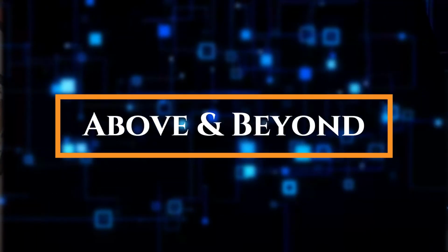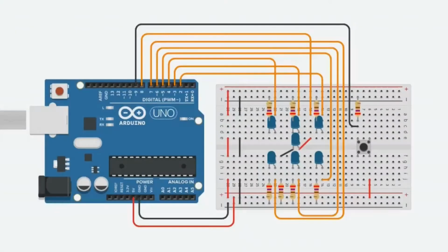Above and beyond. This circuit contains 7 LEDs, 8 270 ohm resistors, and a push button. This circuit also uses 2 to 9 digital pins of the Arduino. At a push of a button, this circuit generates random LEDs to light up as if you were to roll a dice.